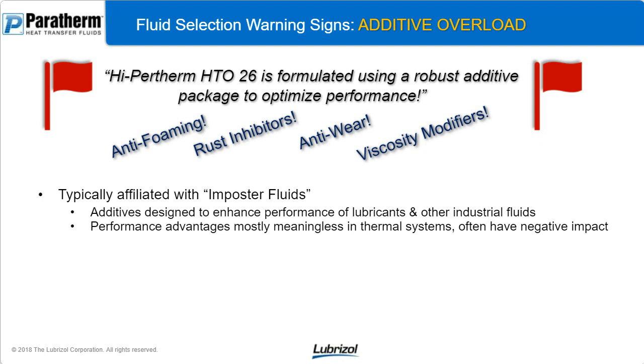They're purposeful for that. But those performance advantages they offer for those applications are pretty much meaningless in a thermal system. You don't need to worry about the foaming or the rusting, or there's no low clearance areas where you're lubricating, worrying about wear, right? And most of the time, they have a negative impact. All those high efficiency properties that we discussed earlier, the viscosity, the density, a lot of times the additive packages that they put in for intentional purposes will actually take away from the efficiency.